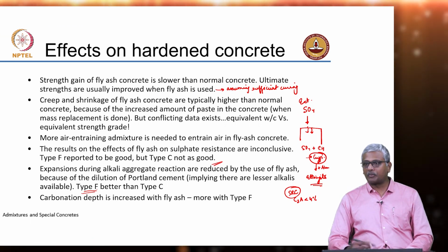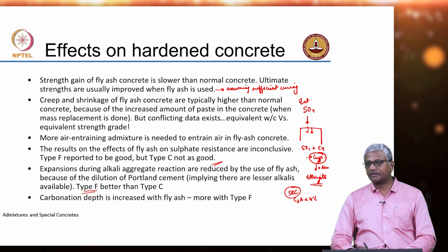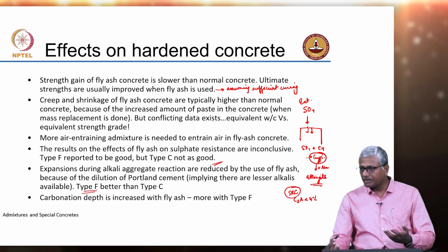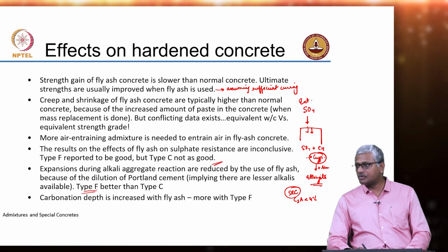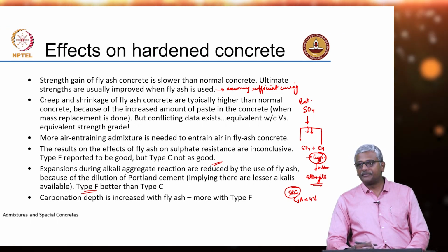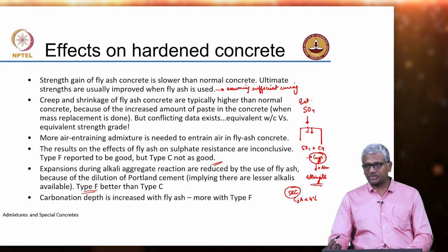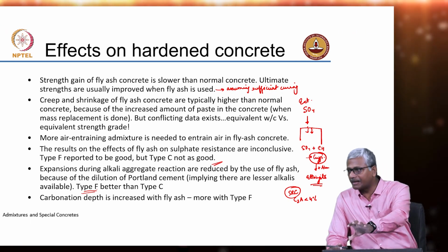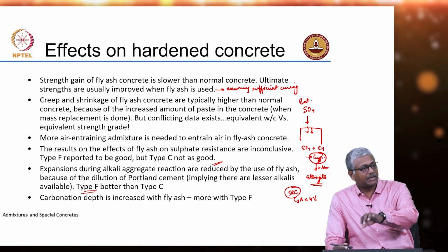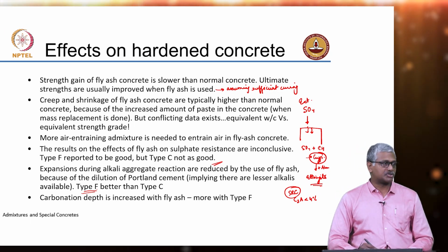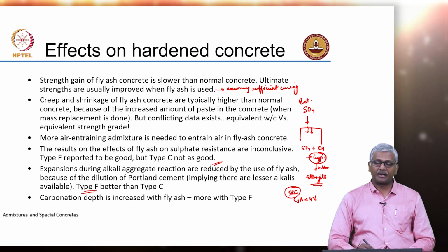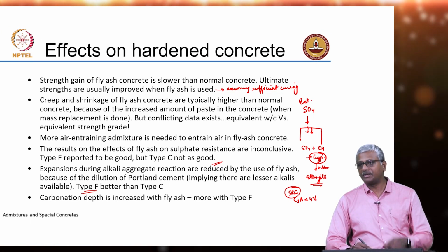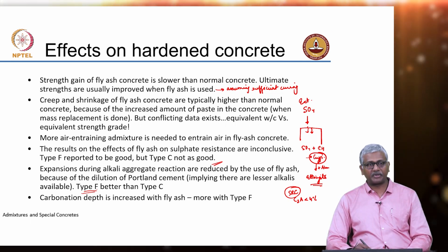What is the other compound apart from calcium hydroxide? Calcium bearing compound. All compounds are calcium bearing, but what is present in large amounts? Calcium silicate hydrate, CSH. So, this carbon dioxide, when it does not have sufficient lime with it to interact, it will interact with CSH, okay, and that is a reaction that leads to an increase in porosity. So, more CO2 is actually able to penetrate.